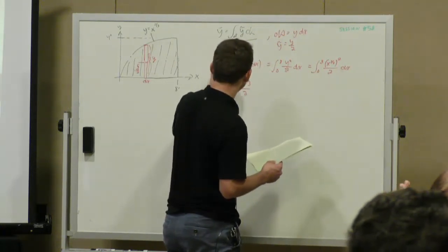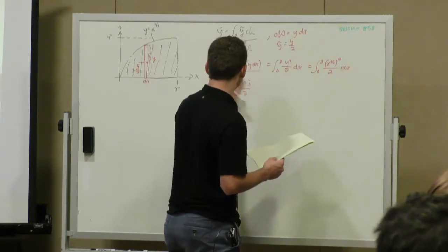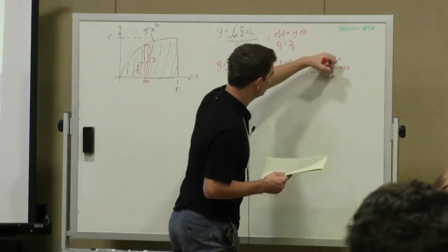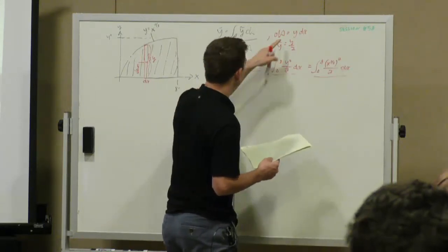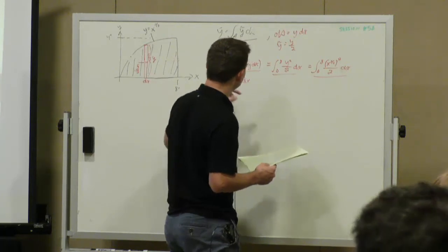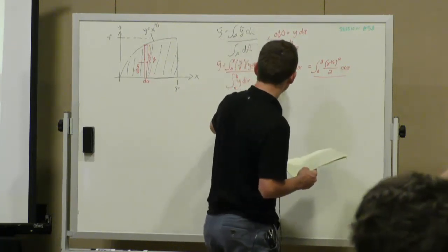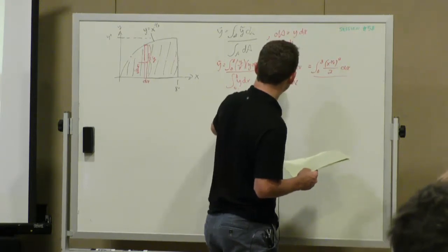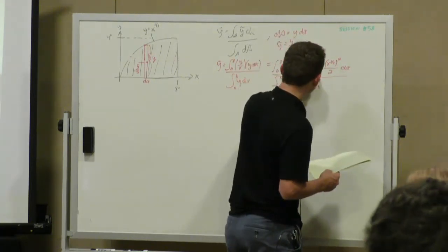And we're also missing the bottom. So we're missing the denominator, which was the integral of dA, which is y dx, 0 to 8. And we substitute y in, x to the 2/3 dx. And just bring that over one more time.